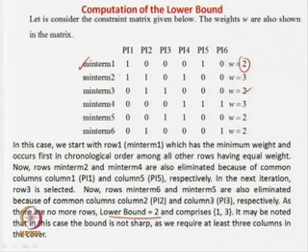So, there is a higher probability of covering this row if you are selecting the prime implicants in some order. But here the number is only 2, or sometimes only 1. If there is only one 1 in the row, you know that it becomes an essential prime implicant. So, the fewer the ones in a row, the more difficult it is to get it covered. We should not call it probability, because all the rows have to be covered, but the idea is that it may be very difficult to cover that row compared to a row which has more ones. So, that is why we do this ordering, and then we start with this one.